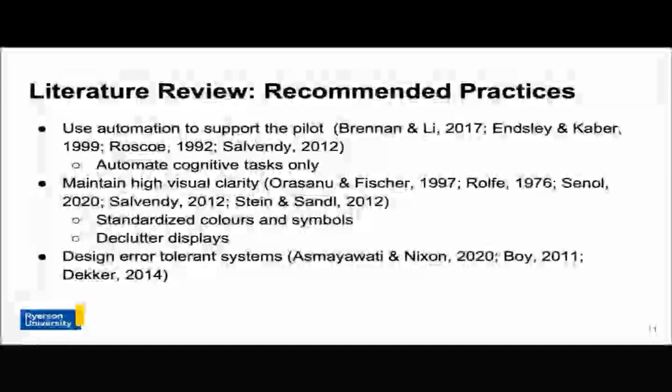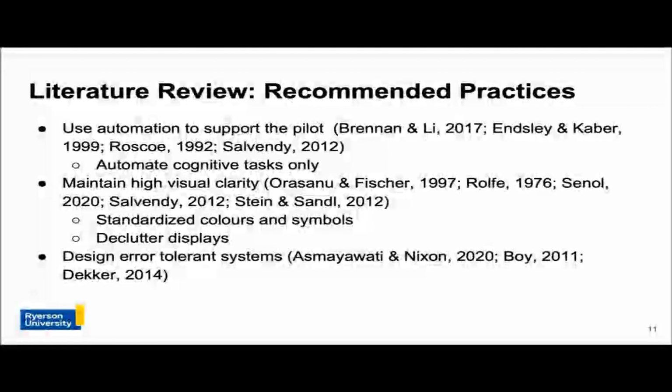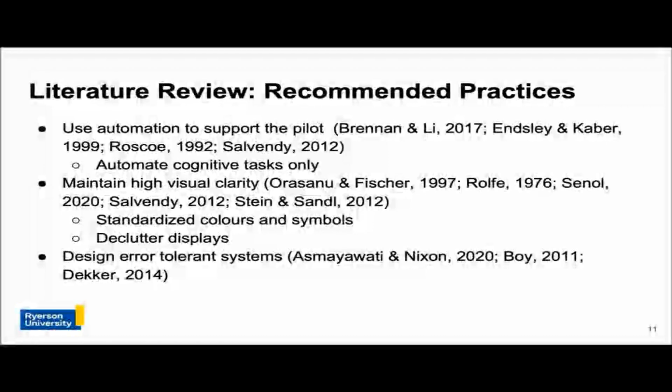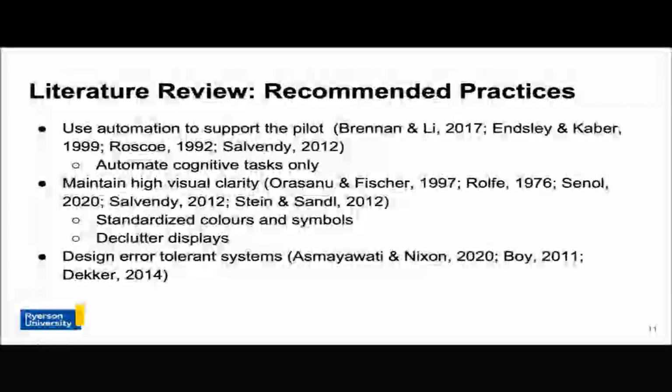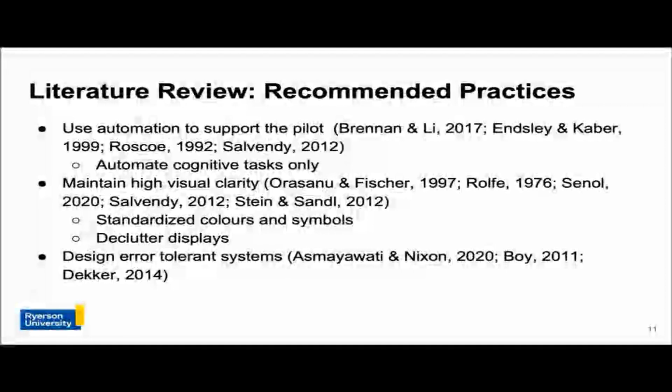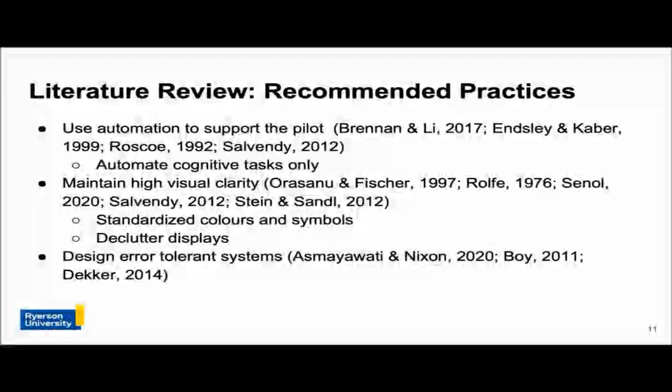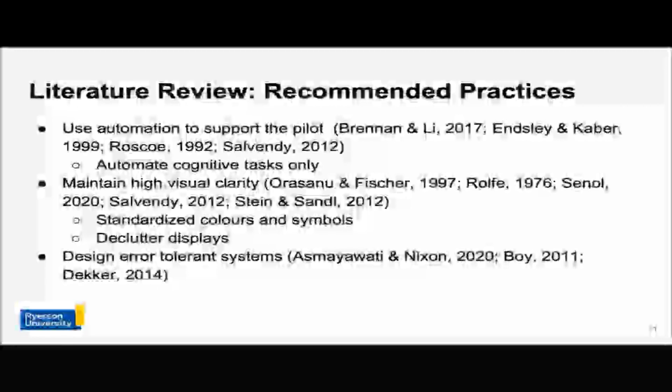Another recommended practice in the flight deck is the use of standardization for high visual clarity. Colors, symbols, and labels can be standardized to help lower the chance of confusion for pilots. In addition, keeping displays free of clutter can help pilots maintain high situational awareness. When displays are cluttered, pilot workload increases as they search for important or desired pieces of information. By keeping displays clear of clutter, pilots are able to find information quickly and easily, which corresponds to lower workload and better performance.